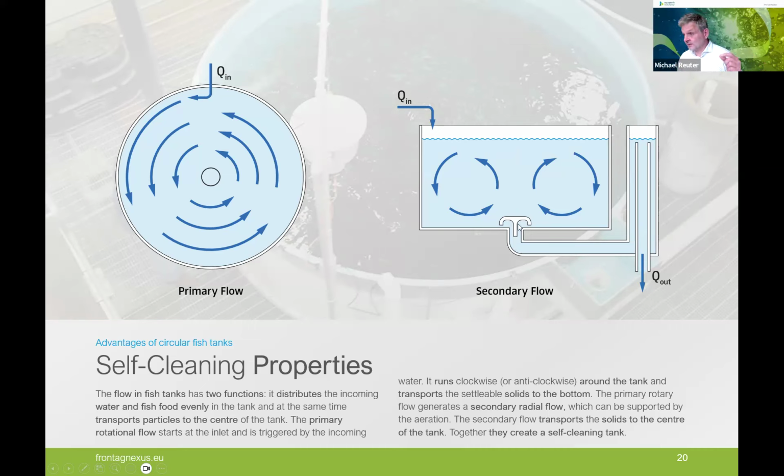If we use a bottom drain, we always have to think about a standpipe outside of the fish tank, because with the bottom drain, we are always risking to lose all the water when we have a leakage. So the standpipe outside will make sure that the water cannot go further down than the height of the standpipe, even though we have a bottom drain.